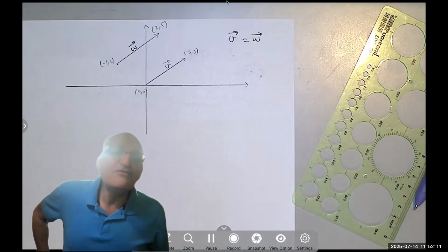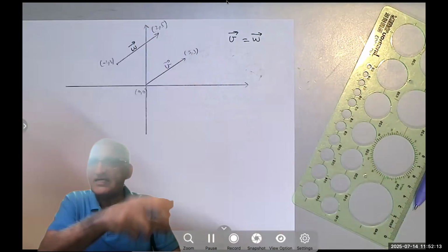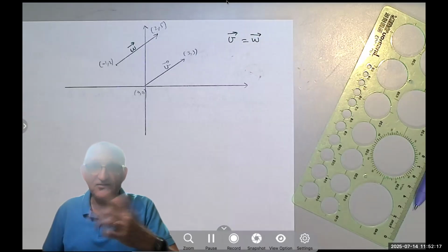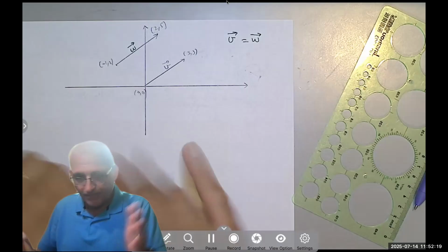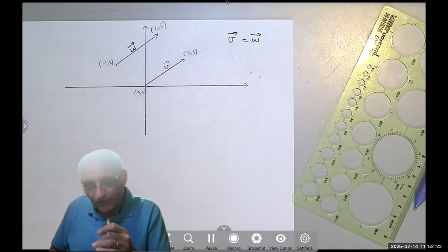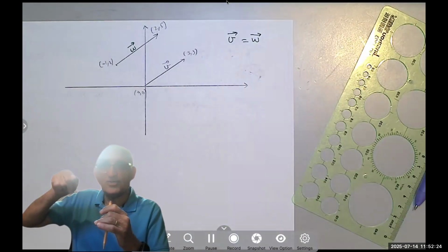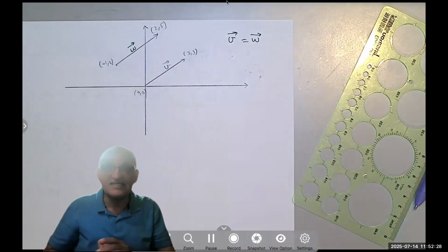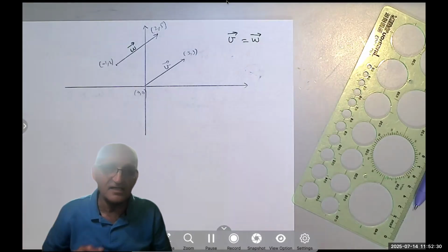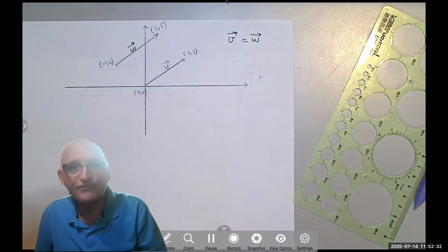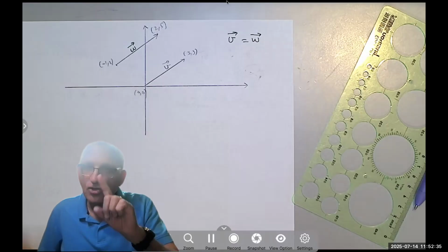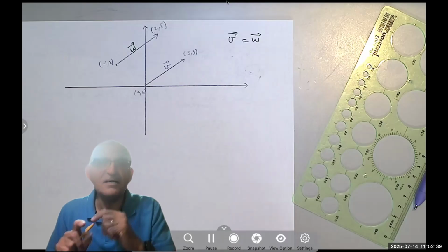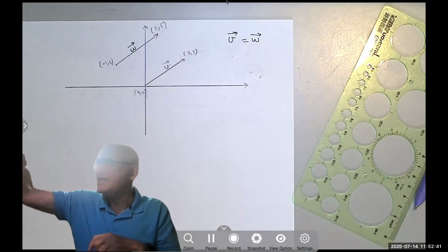And we call that a free vector, meaning you are free to place it wherever you want. Later, we learn that forces are not free vectors. Like I told you, if I have a box sitting here and I push it from down and then move it parallel to itself and move it from up, and this box is very tall and slender, it would fall down in the second case, while it may slide on the floor in the first case. So some vectors are not free vectors, but some are, like couples. You can place them anywhere you want.